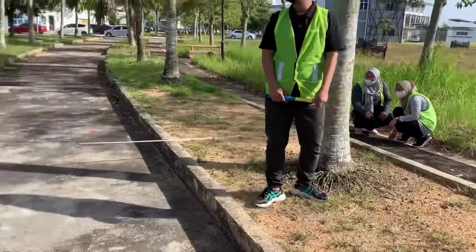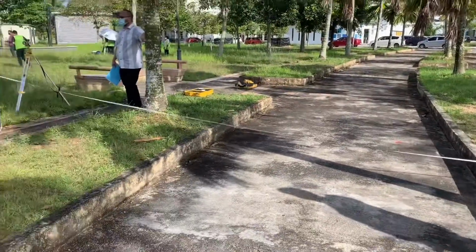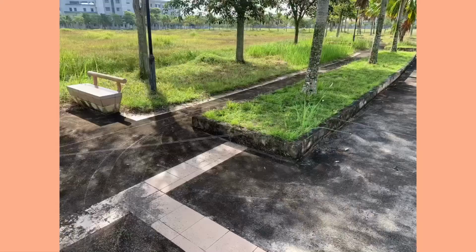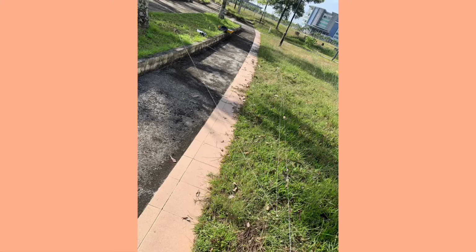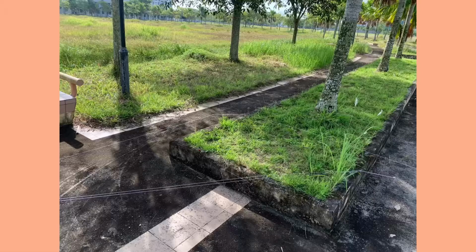The position of point C can be obtained with a measuring tape pulling from D and B according to the measurements of DC and CB. The spikes are fixed and the point C is sufficiently nailed.